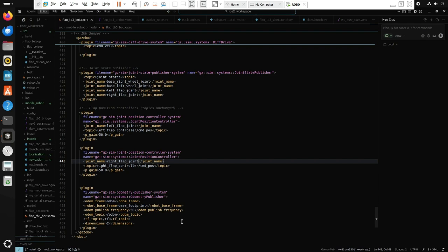So basically in the simulation, the URDF is added into Gazebo, and you can see the robot moving and interacting with the environment. Now let's dive into the technical aspects of the project. The robot's movement is controlled using a differential drive system, where the wheels are commanded via ROS messages.